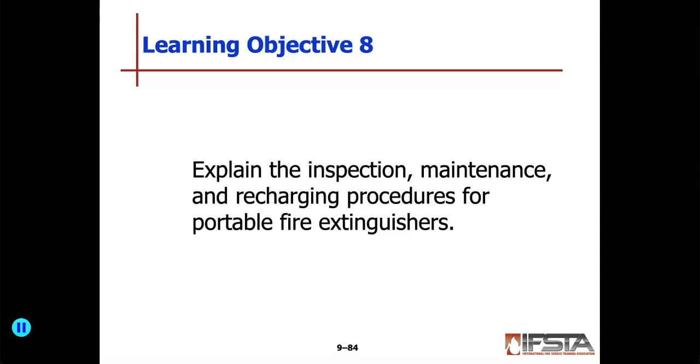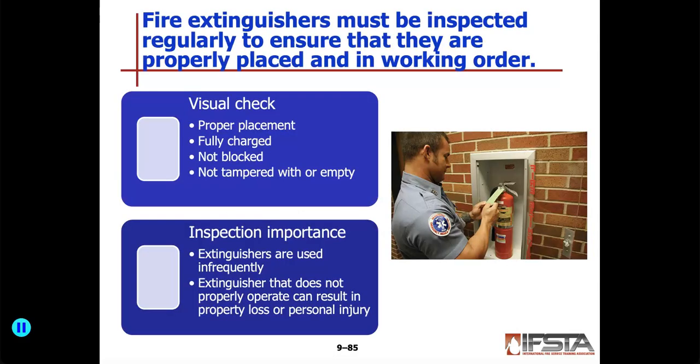Explain the inspection, maintenance, and recharging procedures for portable extinguishers. Fire extinguishers must be inspected regularly to ensure that they are properly placed and in working order. So you see the tag on there. He's doing a visual inspection of the extinguisher for damage, but also inspecting the tag.